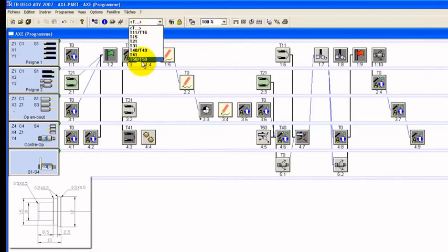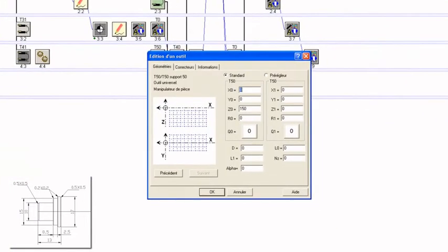On the other hand, for the T15, there is the geometry of the pad manipulator, at 150 millimeters. We will have to change this geometry because it corresponds to the geometry for gripping pads with tweezers. We decided to use the basket and the pad extractor, which is in the counter spindle. So here we will end up with a geometry of about 330 millimeters. Validate OK, and that's it for the information of the tools in the catalog.